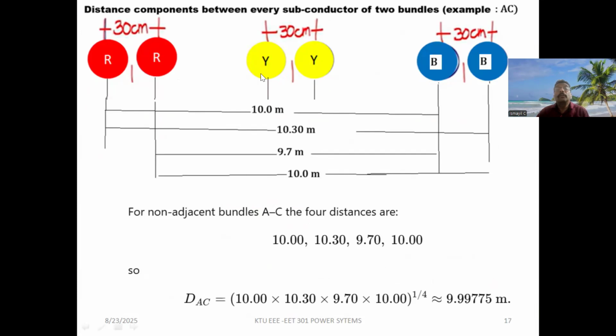Now we will see the equivalent distance between the first bundled conductor and the last bundled conductor, that is R and B. For that, we can write the distances as earlier: the first R and the first B, the first R and the second B, the second R and the first B, and the second R and the second B. So the distances are 10, 10.3, 9.7, and 10.7 meters.